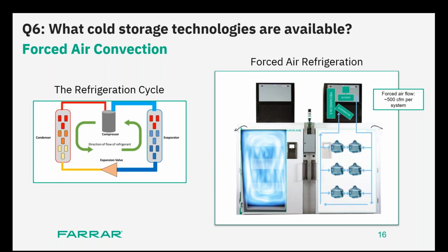So what we have done is instilled this auto defrost function. On a regular basis, you can turn off the evaporator for the refrigerant and push hot gas through the coil, which would melt the ice that has formed around the evaporator. You collect it in a drip panel and it comes out. And during this entire operation, you don't have to shut down your freezer. It could be fully operational. And that really saves your precious samples.